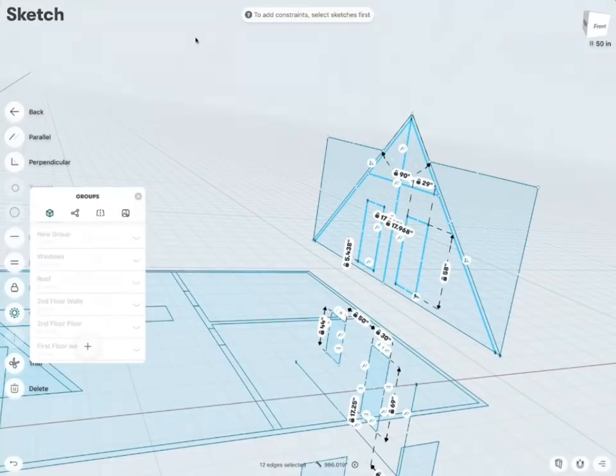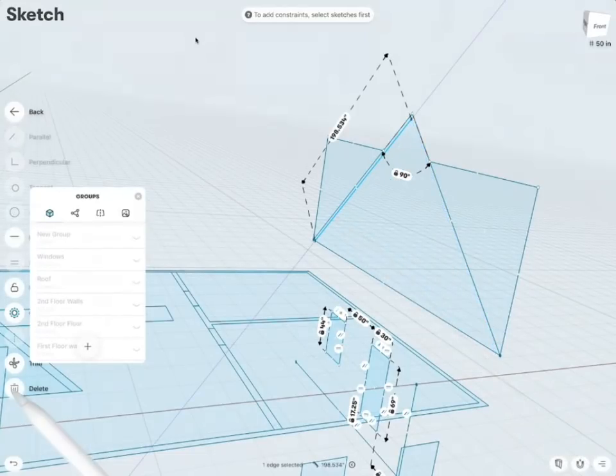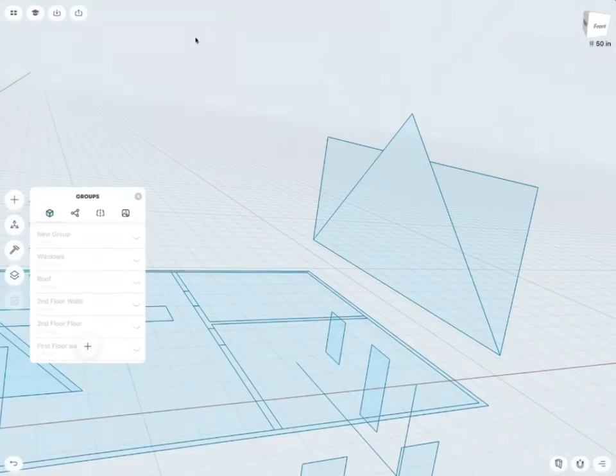There, and delete that one too. So that was the original triangle from which I created the roof body, and then we shelled it, and then later we added the additional elements to it. So similar to the first floor, try to approach drawing the sketches based on how you have to model first. Now don't spend too much time drafting the sketches and then start modeling. Add details on the fly as necessary.